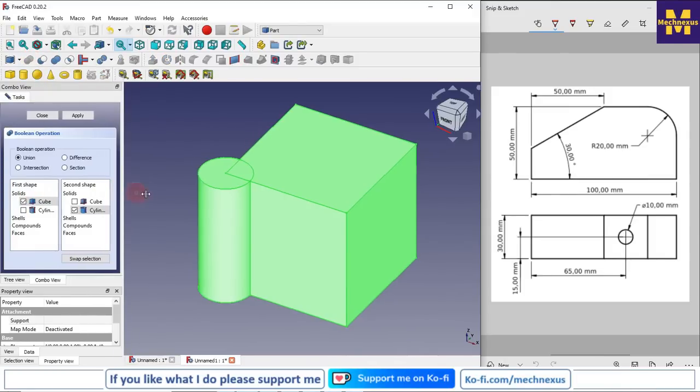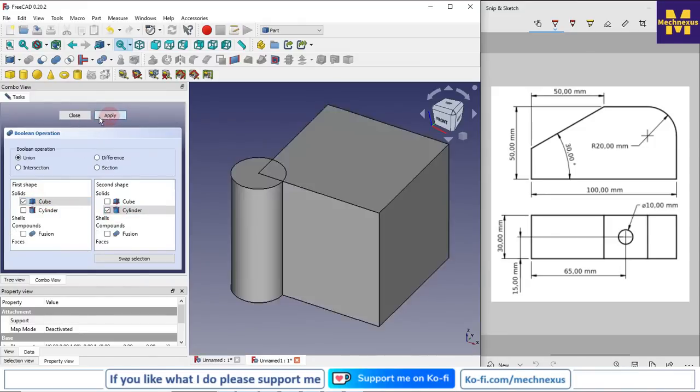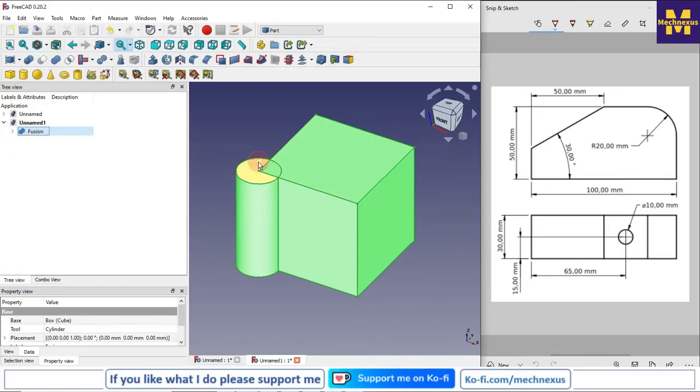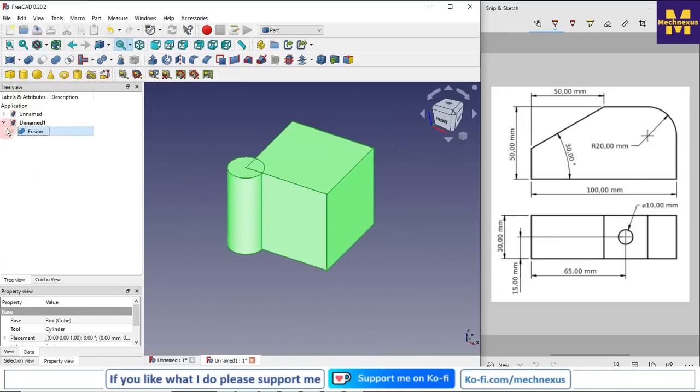Here in a dialog box, FreeCAD is asking, do you want to combine cube and cylinder? I will say yes, and I will say okay. Now if I go to the part tree, I am seeing a single body. Previously there were two, one was the cylinder, one was the cube. So this is the fusion operation.